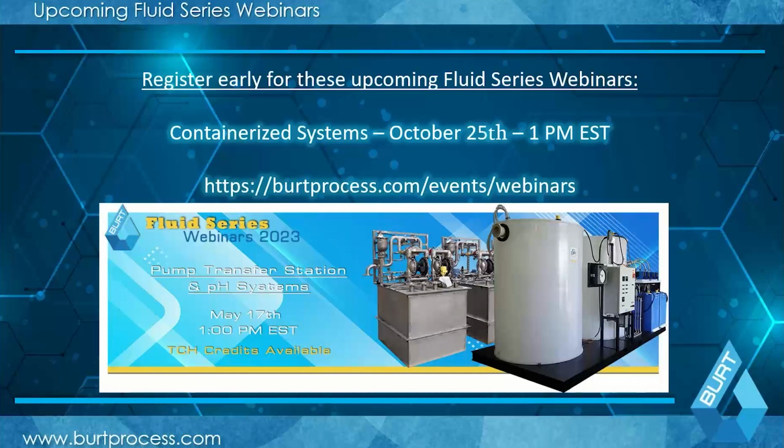And that's where you get into some of the nuances of lift station designs, where you have to look at what those inverts are, what your flow rates are, what those volumes are. Because you also don't want to go too deep, because now excavating is very expensive in those cases. So if this line's 7 feet deep and it's 200 gallons a minute, and I need to put in a 1,000-gallon tank and go 7 feet deeper, that's not a very practical solution at that point. That's where you get a lot of the engineering that can be done. And there's a lot of different solutions to solve some of those different issues.